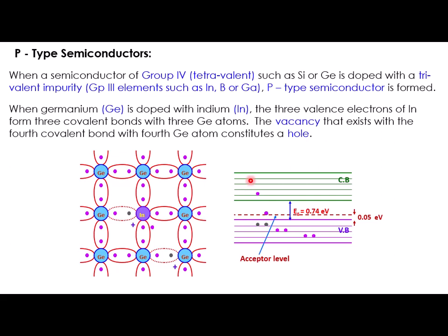At the same time, some recombination will also take place. As a whole, here the holes are generated due to two reasons. One is intrinsically generated holes, by exciting electrons from the valence band to the conduction band, and the other is holes given by the acceptor atoms, whereas the electrons are generated only due to the intrinsic region by exciting electrons from the valence band to the conduction band.